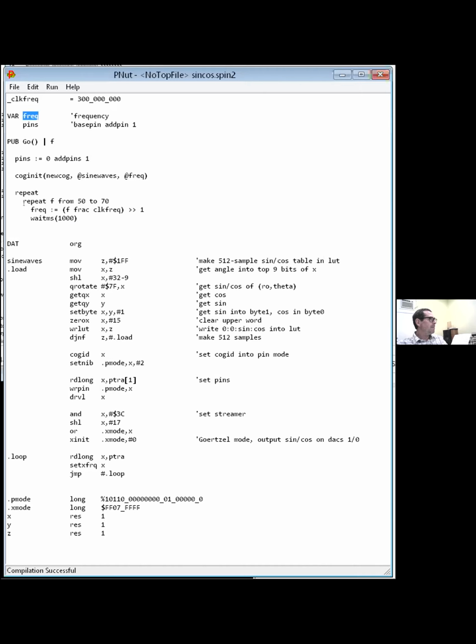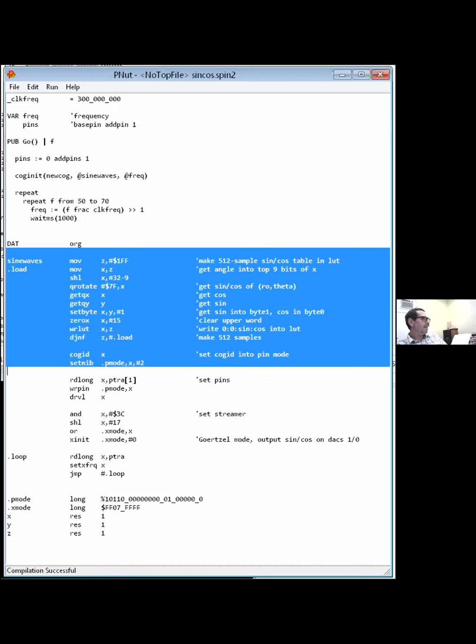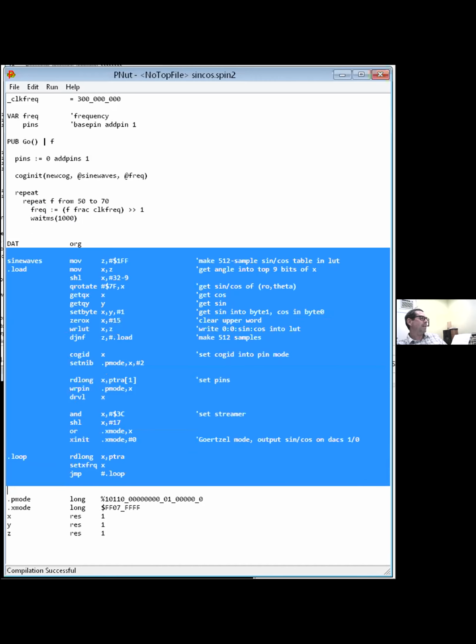And we communicate to it through this variable. So we need to have the cog keep running because we need its streamer to keep functioning. So this here probably, you know, if the PASM program's running in cog 0, this winds up running in cog 1.